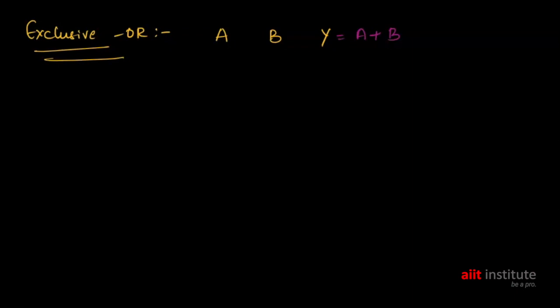So, for this 0 0, 0 1, 1 0, 1 1 are the inputs. As the name itself says here, it is exclusively OR. That means if both are same, then it is low. If both are different, then only it is high. Okay, so here we have different only in these two scenarios. So only in this region it will be high. Remaining everywhere it will be low.